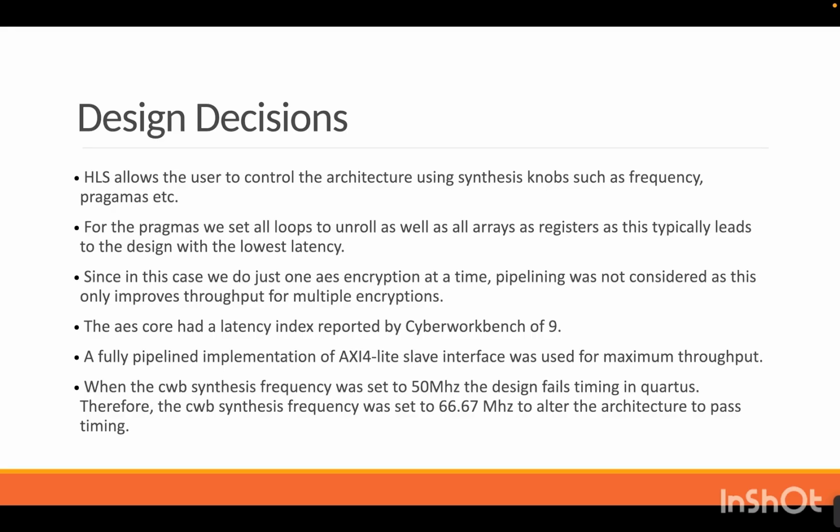For communication, we used a fully pipelined AXI4 Lite slave interface to maximize data transfer efficiency between the HPS and FPGA. During timing closure, we observed that setting the CyberWorkbench synthesis frequency to 50 MHz caused timing violations in Quartus. To resolve this, we increased the synthesis frequency to 66.67 MHz, which allowed the tool to generate an architecture that successfully met timing constraints.